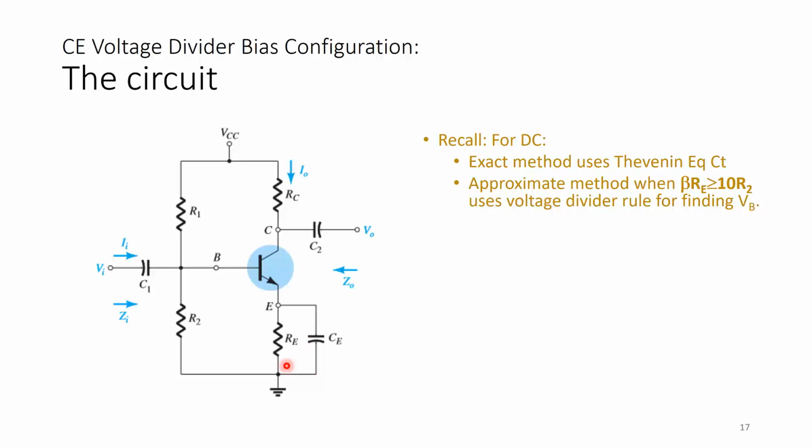Before we go on, we know that we have to do DC analysis before we go into AC analysis, because we cannot solve a circuit of an AC amplifier without setting it into the Q point. So either the question itself has already calculated it for you and gives you the DC parameters, or you will have to do DC analysis.